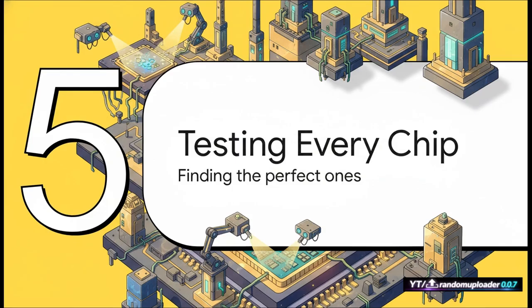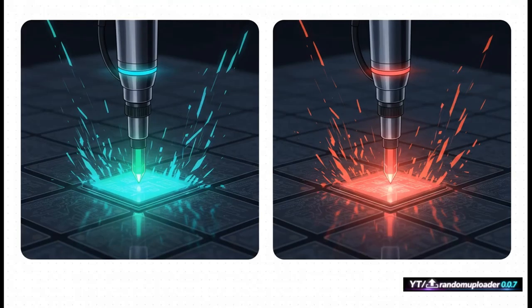So, after building this entire microscopic city, we have to make sure every single part of it is perfect. At this scale, the tiniest little flaw can cause a complete failure. So it's time for some serious quality control. Each potential CPU on that wafer is called a die. Tiny automated probes come down and run a whole bunch of electrical tests on every single one. If a die passes all the tests, it gets marked as perfect. But if it fails even one of them because of some tiny flaw in one of its billions of transistors, it's marked as defective and gets tossed. There is just no room for error.